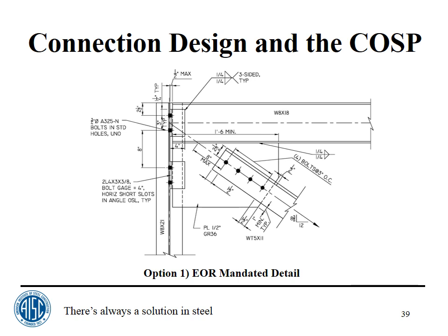For instance, you see an 8-inch dimension here from the lowest bolt in the beam to the highest bolt in the gusset to column web connection. If you move that, it may change the force distribution. I don't think it will particularly in this case, but it might. If this were a column flange, it definitely would.